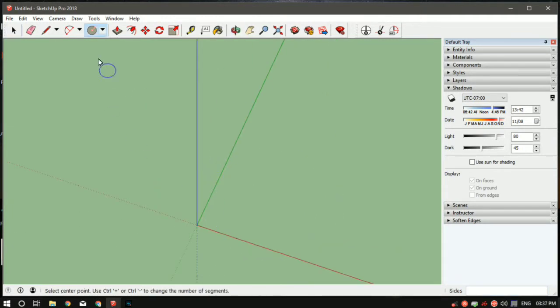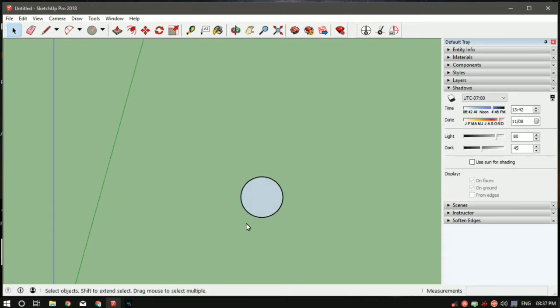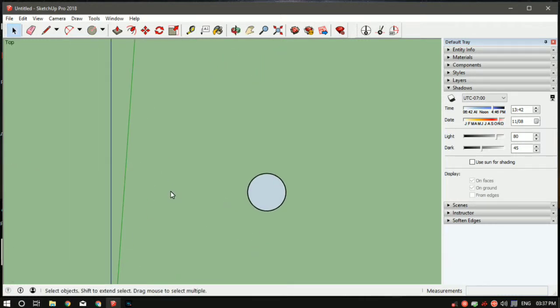What I'll do is let me make a circle first. Command is C, and the radius of the circle will be 10 feet. Press enter. Let me zoom in. Now I want to make a polygon. The definition of a polygon is an n-sided object where n takes a value more than 4. If the number of sides are more than 4, then it's a polygon. Previously we made a 4-sided rectangle. Now let us make a 5-sided polygon, or in mathematical terms a pentagon.